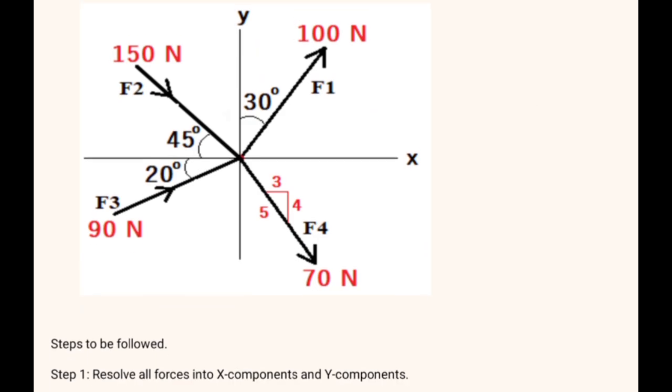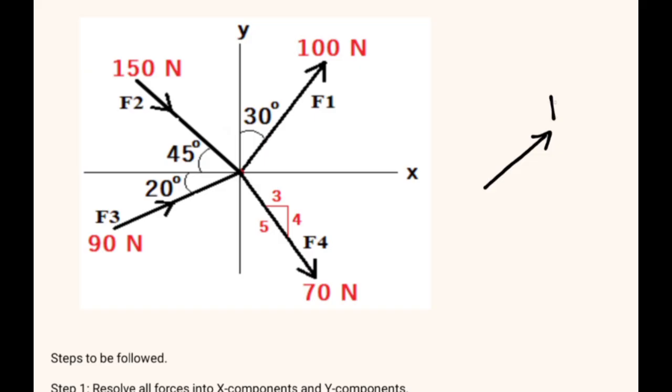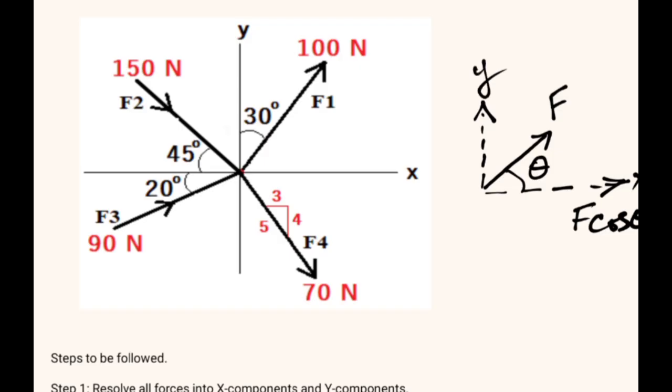If I have a force here which is given as F, and this force has an angle of theta with some direction, so its component in this direction will be F cos theta. And suppose this is your x-axis and this is y-axis, the component in the y direction, which is at 90 degrees with the x-axis, will be F sin theta.